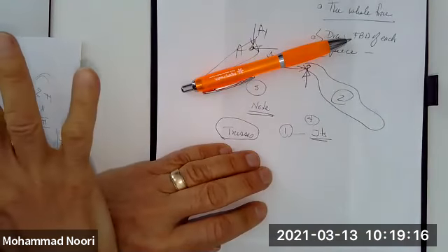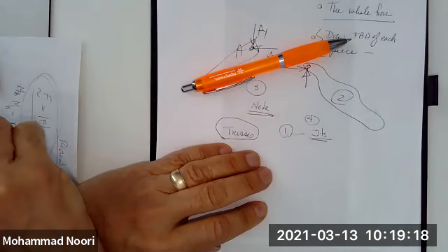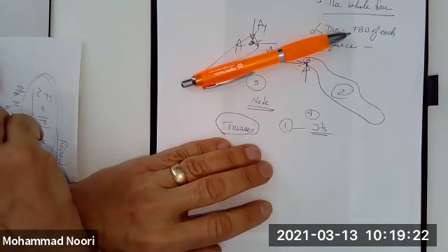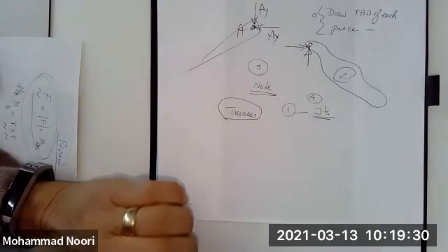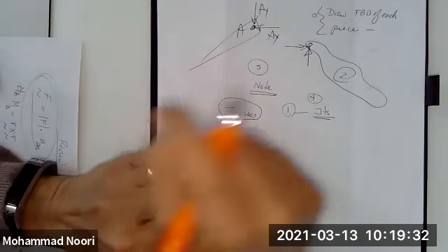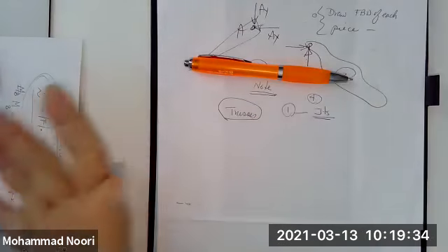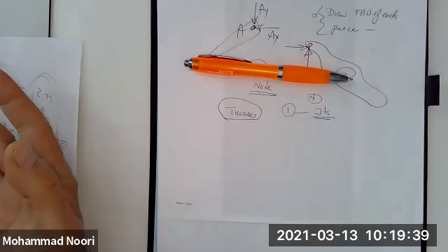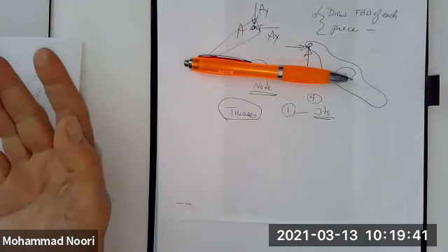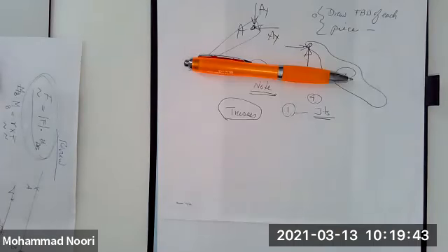And how do you do that? Again, step by step. Step number 1. What is step number 1? Zero force members. You do identify all zero force members in a truss, because you may have been given a truss with 15 members. Once you identify all the zero force members, you may end up only with 3 or 4 members that you need to find. So identify.